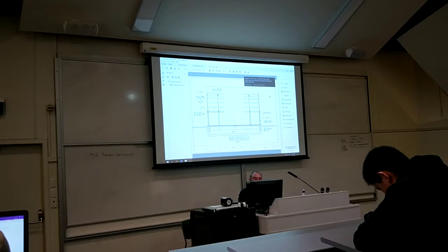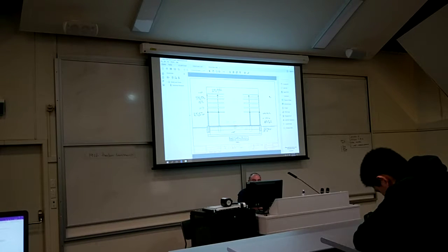I haven't completed the elevational view. I've given you a bit of a clue of what it should look like, but you're going to have to complete that yourself to get full marks on that one. It's an elevational section, which means somewhere along the line we've taken a slice through in the other direction. To me, that's the trickier one to do compared with the two sectional views.